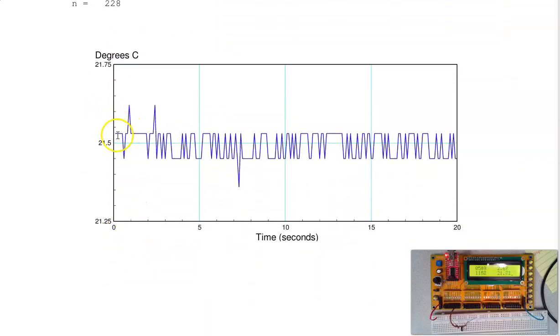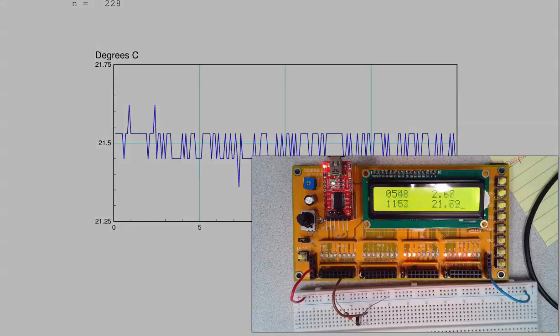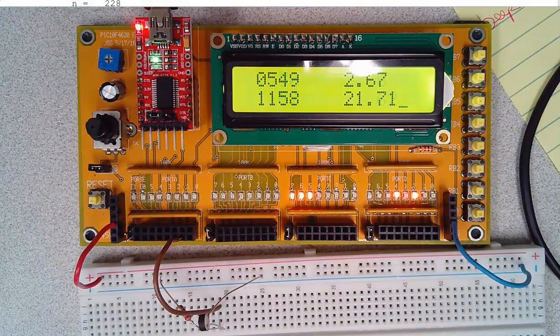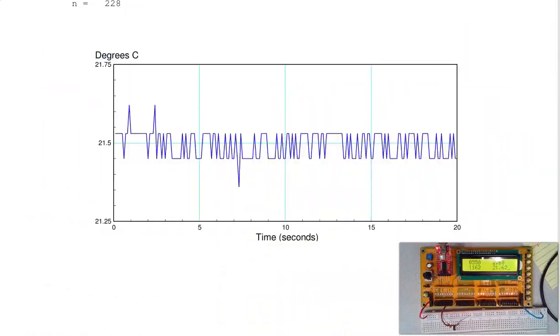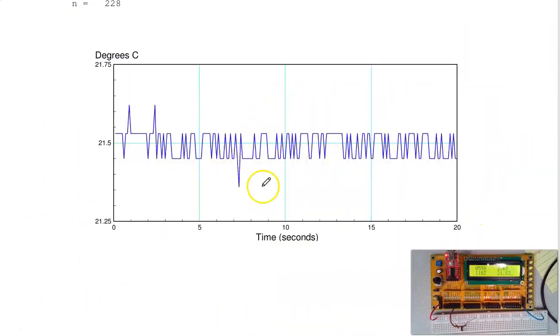What I'm looking at are quantization levels. So the A to D converter is an integer, 0 to 1023. Each one of these is one count, 1 bit. So that's kind of what the data looks like. To get it smoother than that, it's just going to be noisy. If I had a high resolution A to D, like a 12-bit, 14-bit, it'd be smaller. If I had an op-amp circuit, rather than just take a voltage divider and read it, I could amplify the voltage, spread it out some. I didn't do that. I just took a voltage divider. Keeps it easy.